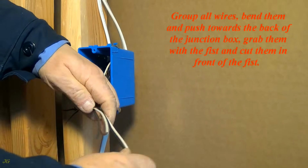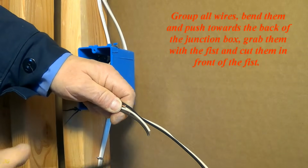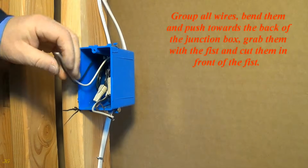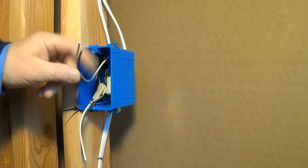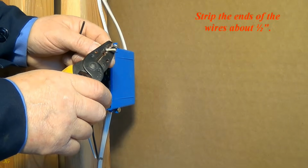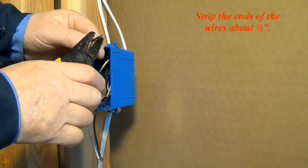Group all wires, bend them and push them towards the back of the junction box. Grab them with the fist and cut them in front of the fist. Strip the ends of the wires about 1/2 inch.